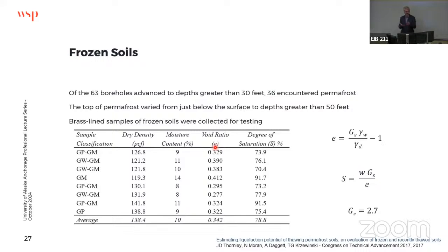Yeah, because now you're talking about the moisture has to go somewhere, right? And so in consolidation theory, you have one-way drainage and two-way drainage, right? Where if you have a clay that you're loading up and you give it two drainage paths to try to get the moisture out faster. Well, if you've got a frozen front on one side, and you only have one-way drainage, your consolidation takes twice as long. Yeah, when you're frozen on top, it doesn't go anywhere. Right? That's right. It's just stuck. Yeah. And you hope that's the case forever then, right? Yeah, yeah.